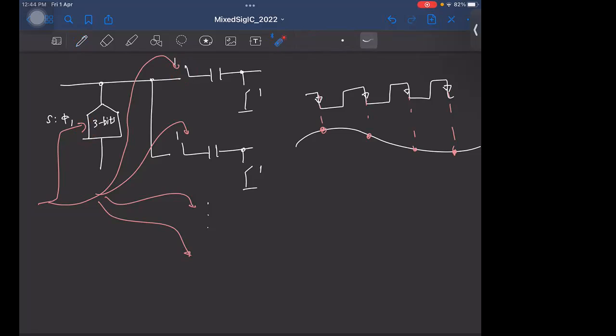So what kind of mismatch? Let's say the clock here is something like this. Okay, this is phi 1 we are generating here, and this has to be routed long, and it has to reach the first ADC, let us say. So obviously the generated clock will reach here after some delay. So which means the clock here also will have some different delay, right?